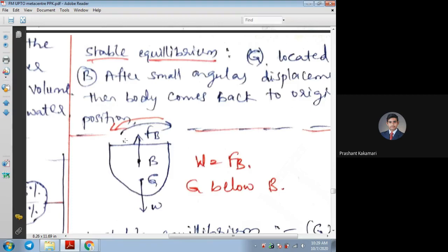The couple generated because of high loads on one corner of the ship may cause sinking or instability, and it may sink at any time. So loading of these bodies should be made equally from all corners, starting from the center, so we can equally distribute all the loads.